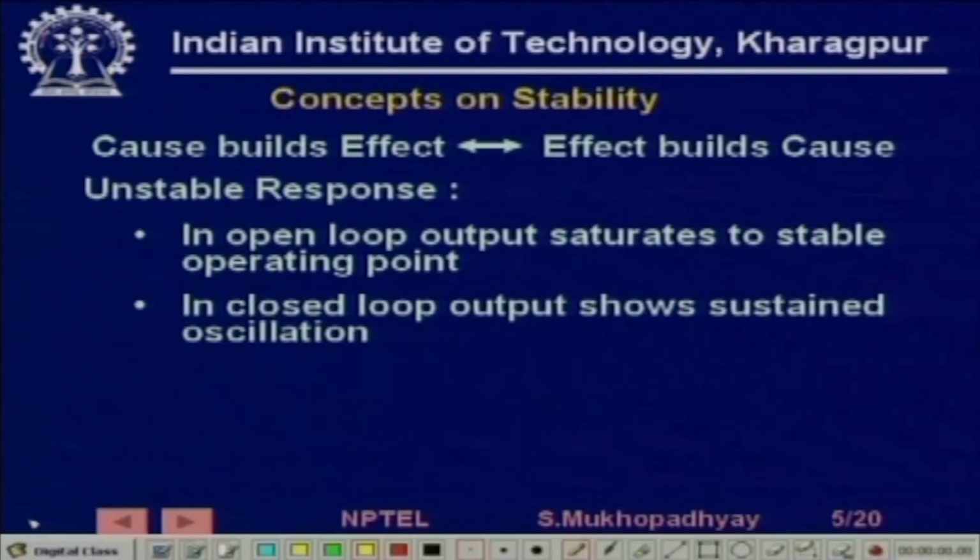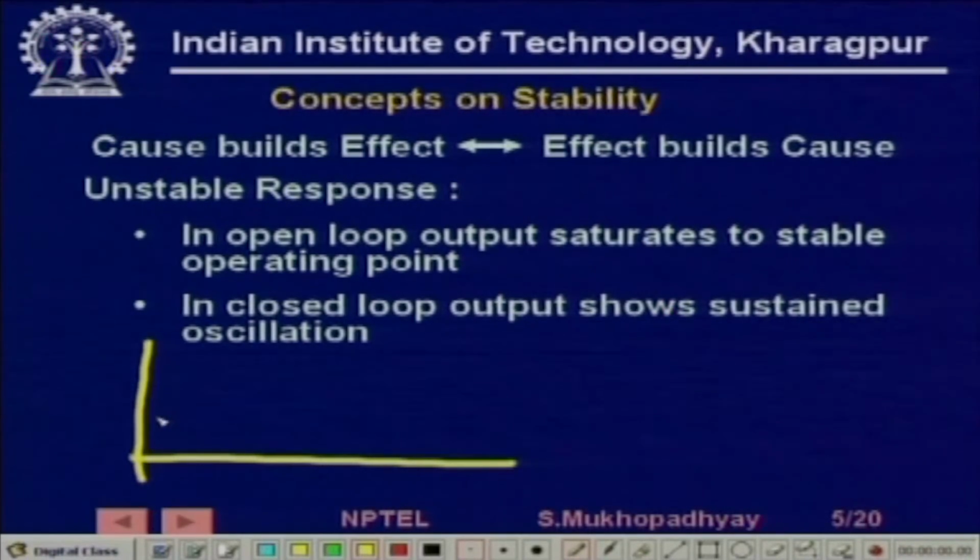Taking the old example, if the torque speed curve is around this point, and it is operating here, it will tend to move away, but the controller will control, let us say, the motor terminal voltage, and it will reduce the torque so that it comes back. Again when it comes back, it will have a tendency to move this way, and then it will have a tendency to move the other way. So, again the controller will move it up.